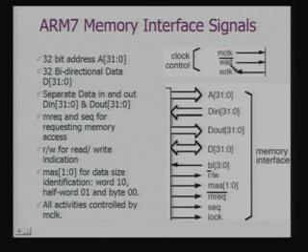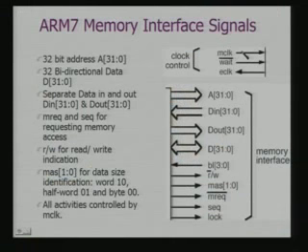When my memory is slow, for a memory access, the processor has to wait. So, the memory module has to tell the processor, please wait till I provide the data. Okay. So, in that case, this wait signal becomes important. That is why I am saying that your internal clocking or internal operation is controlled through a combination of MCLK and wait signal.